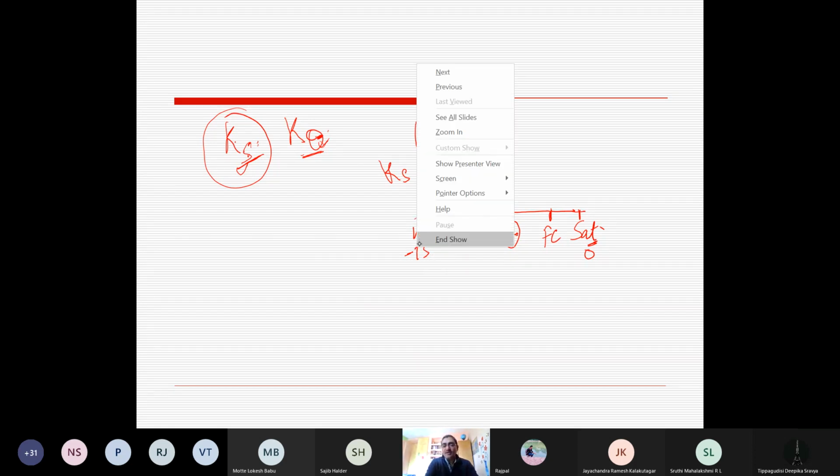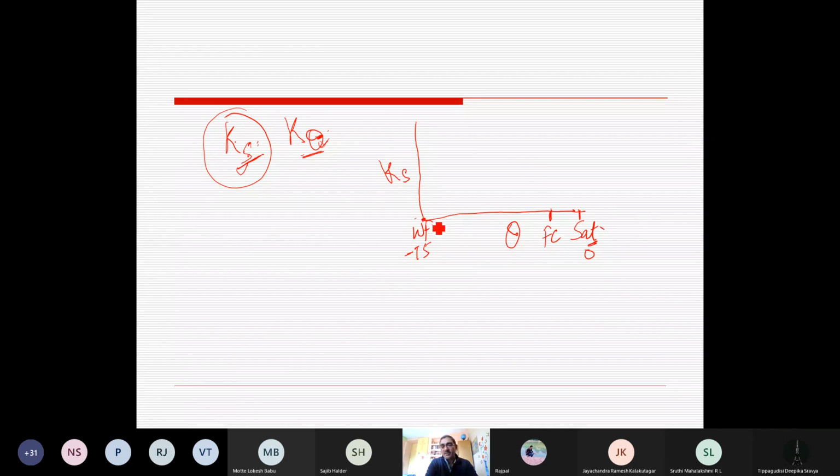So once it is wilting point range soil characteristics, suppose we are applying water on this soil, which is completely dry at wilting point characteristics. What will be the output at the bottom of this soil? Q will be 0. Yes or no? Yes, sir. And what is hydraulic conductivity? When a soil sample is subjected to hydraulic head, there must be flow. So at this wilting point soil moisture content, there is no outflow, so hydraulic conductivity is 0.